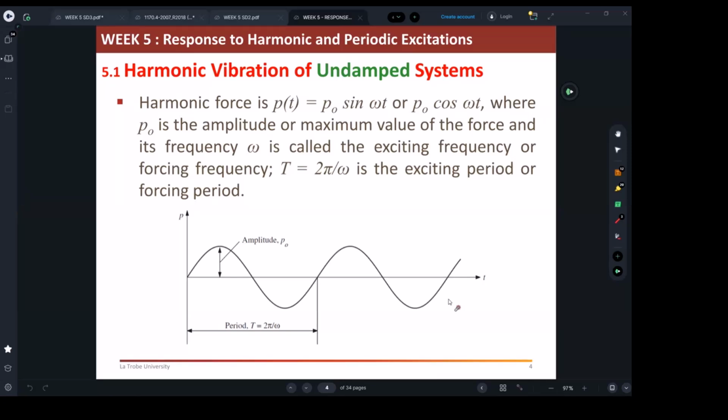We're calling it viscous damping. So starting with the simple one, no damping, no viscous damping, no shear frictional damping. That was the last example we did last week, where we had the shear pads, and as we said, it can give us some damping mechanism. So consider that it is not in the system. It's just a system under forced harmonic vibration and no damping mechanism inside it.